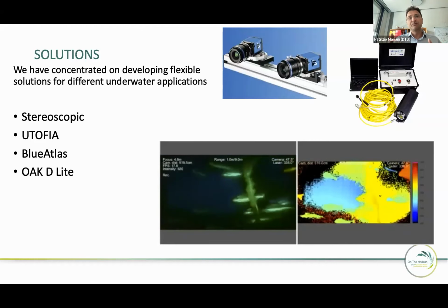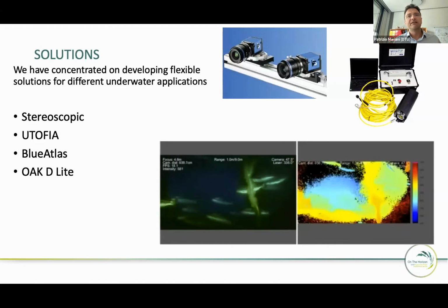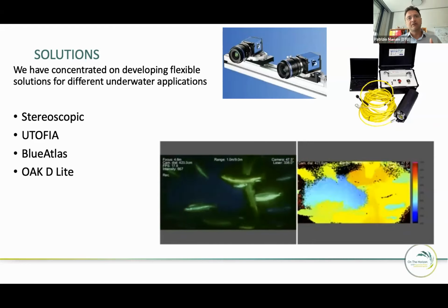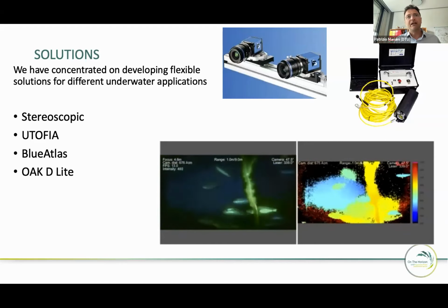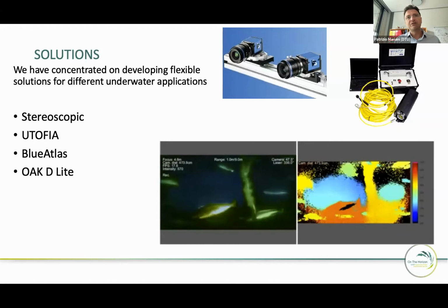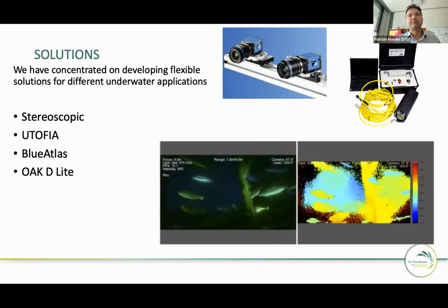And then the camera is tuned with the timing of the laser in order to get the images. The advantage of that is that you filter out all the backscatter, and you have an additional element that you know the distance of the object, and so you can reconstruct the dimensions in 3D.